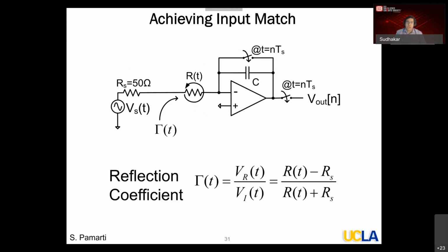Next, let's come to the impedance match. Now we already know that getting impedance match in mixer-first and N-path is not an easy task. It's more complicated than, for example, getting impedance match in an LTI system. Here I have a situation where I am intentionally changing the resistance, and that too by two or three orders of magnitude. So is it possible to get input match there?